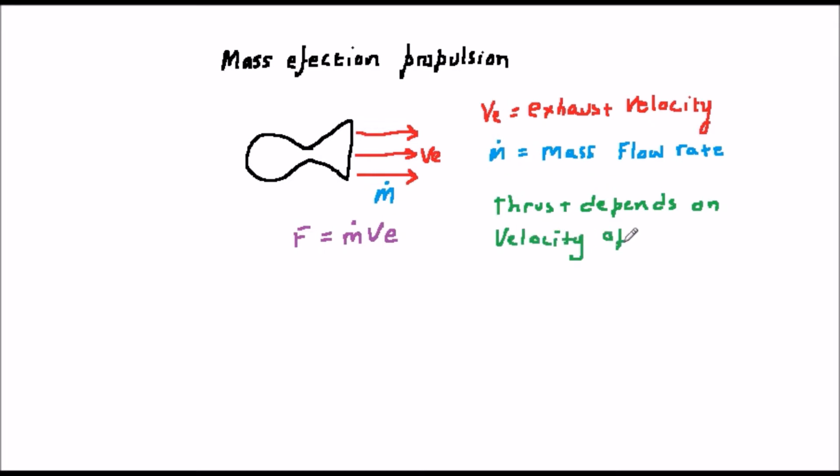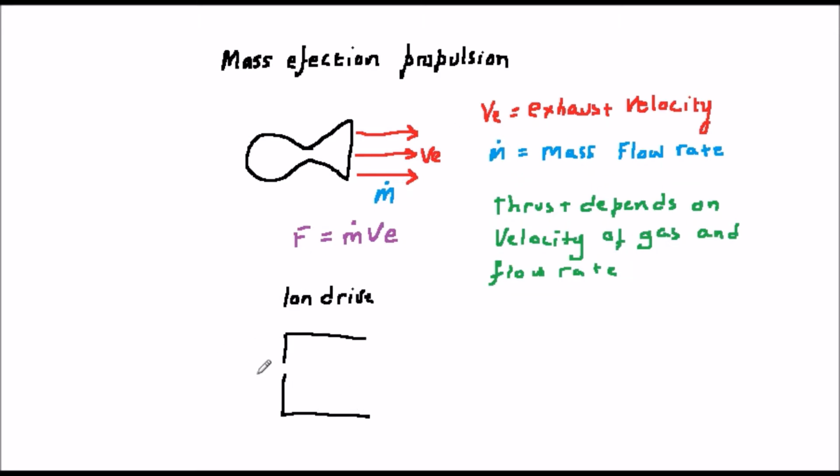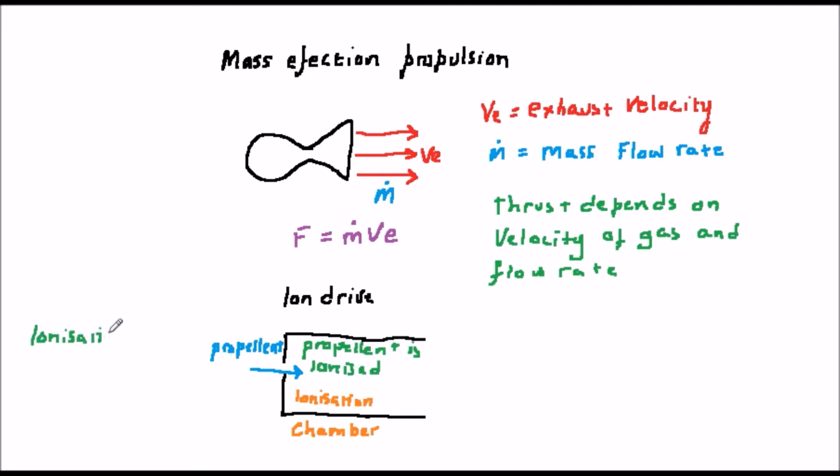The most familiar type of this engine is a rocket, but a traditional rocket is not practical for interstellar travel because the vehicle can't carry sufficient fuel to generate enough ejection mass, and combustion can't provide a high enough exit gas velocity to achieve very high speeds. One alternative is the ion drive. This works by electromagnetically accelerating charged particles, that is ions, through the exhaust. These can reach very high speeds, which compensates for the low mass flow rate.